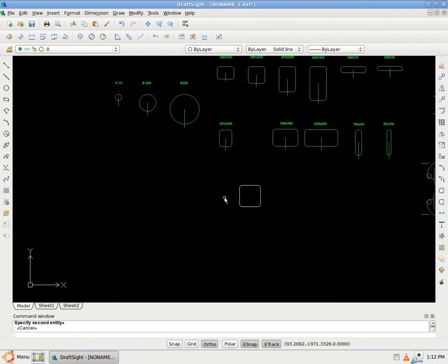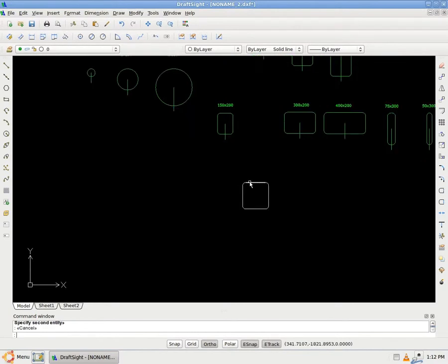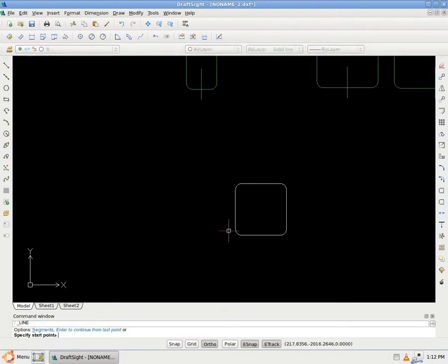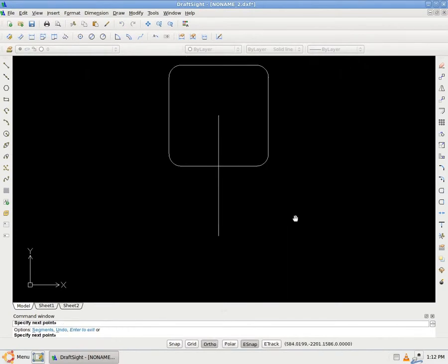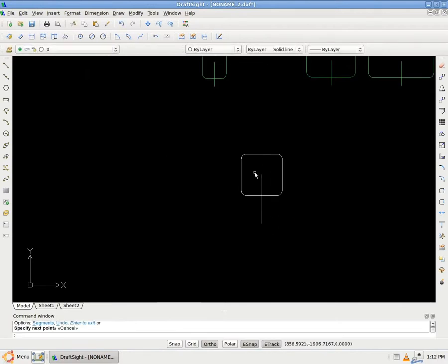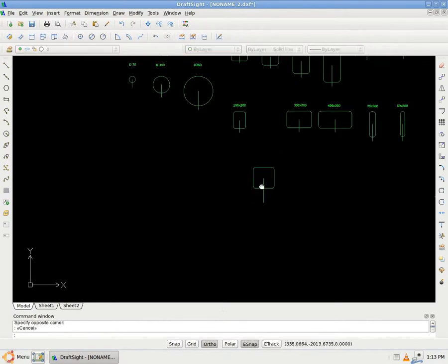After drawing the vacuum, you need to find a point that you will use to place the vacuum in position. It can be the center or a corner. From this point, draw a line in any direction. It doesn't matter where you end the line, because, to place the vacuum, we are only going to use the start point of the line. The machine will place a cross laser on this point, so that you can place the vacuum exactly where you have designed it. Now we will make the vacuum a block.